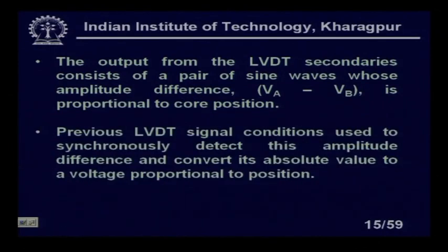The previous LVDT signal conditioners, we knew already, we made a lot of adjustments. As I told you, we need some signal conditioning circuit to kill the null voltage, to kill the phase difference between input and output. Previous LVDT signal conditioning circuits